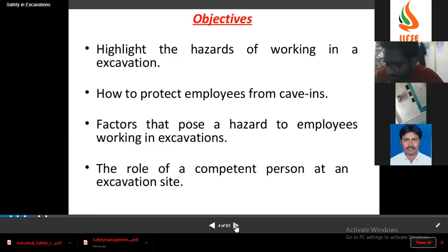No problem. Actually, what you have asked is, before going into the confined space, based on the precautionary measures, the first thing to do is to have a multi-gas detector and test the gases. That is the first primary thing to do, and we will talk about this when we talk about the precautionary measures. What are the hazards in confined space, sir?